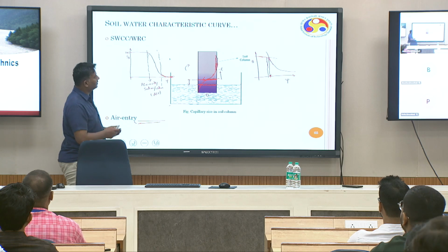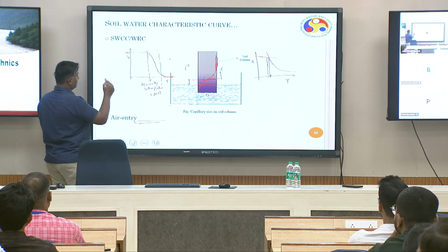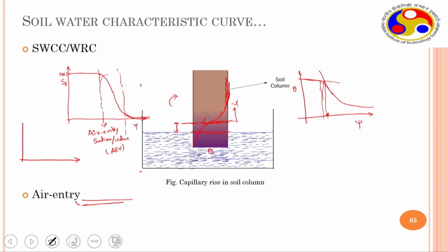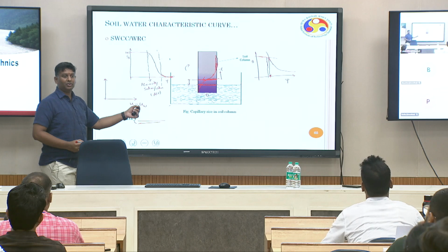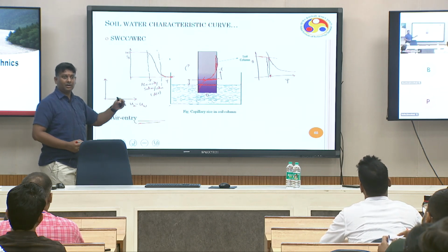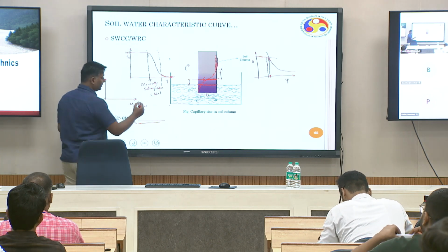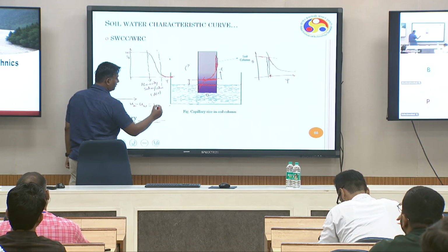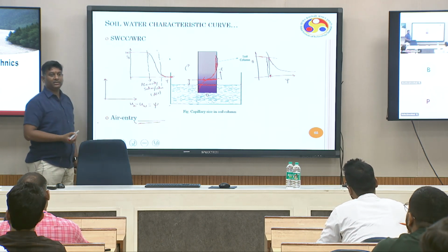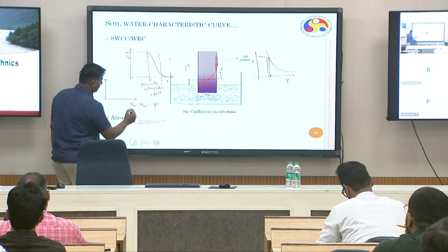So if I describe the soil water characteristic curve, so this is UA minus UW, right? So how much water pressure has dropped or potential dropped against a reference potential, reference pressure, that is air, that is UA minus UW, which is a positive value. We give a sign something like this, psi, suction, which is representing suction in kilopascal only.